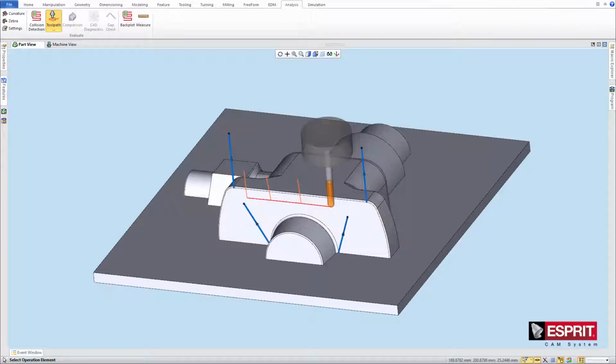For example, as the tool moves toward the conical feature, notice how the vector chain starts to influence the tool axis orientation as the tool approaches, until the tool axis orientation is approximately aligned with the vector chain when the tool reaches the vector chain. Then, as the tool continues toward the next vector chain, the next vector begins to influence the tool axis orientation. At the midpoint between the 2 vector chains, the tool axis orientation is an equal blend of both vector chains.